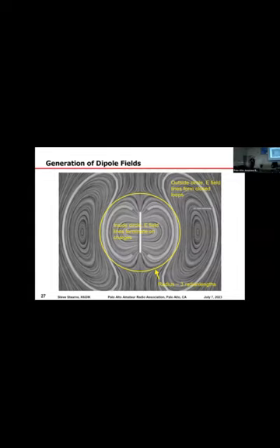So that's why the so-called impedance of free space is a real number. It's not a complex number. It's not an imaginary number. It's a real number because the electric field and the magnetic field travel together. They coexist, they travel together, and they're in phase. Whereas inside, they're in quadrature phase. There's a 90-degree phase shift between the electric field and the magnetic field inside of that circle. That's kind of interesting. Okay, let's move on to the next slide.